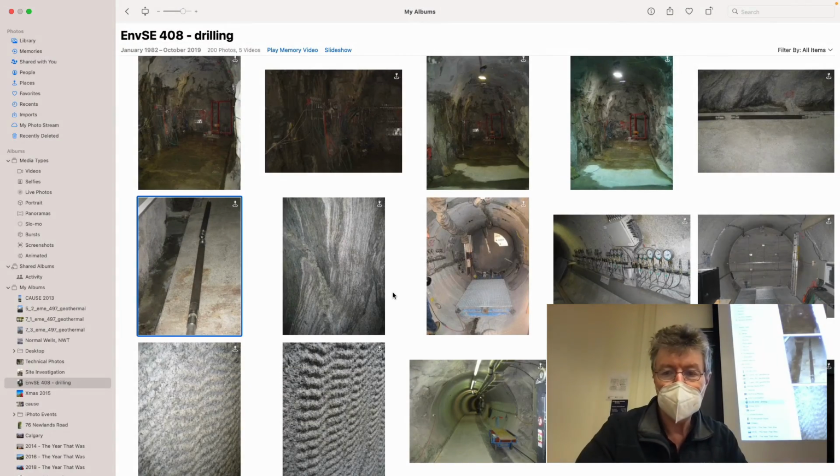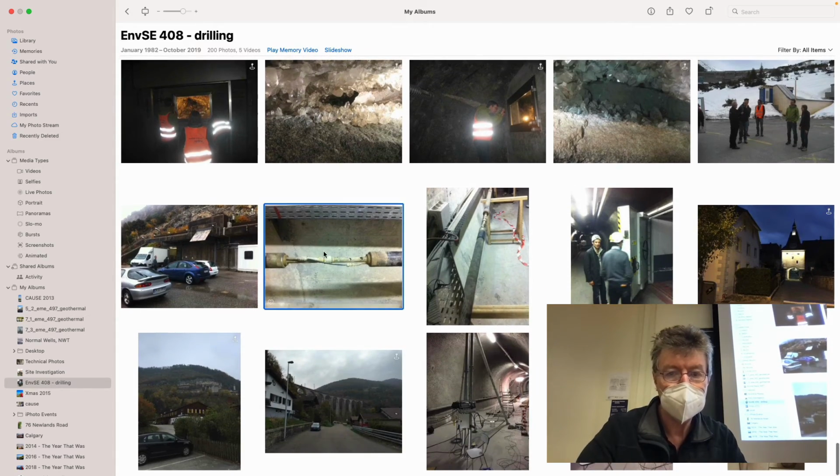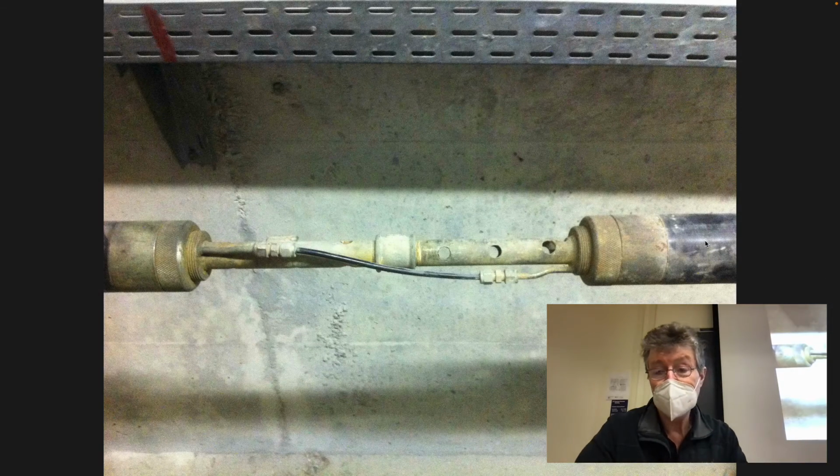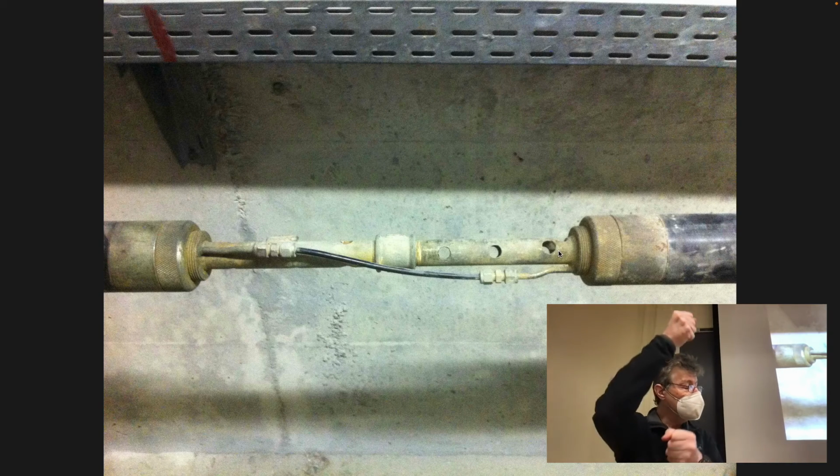And the other one that we saw was one that was actually set up to do that. Here. So this is the upper or lower packer, the gas line that links them, and this is the area where you either measure pore fluid pressures somewhere in this zone, or you'd inject fluids into the straddle zone. The straddle zone would be the zone between the two packers.